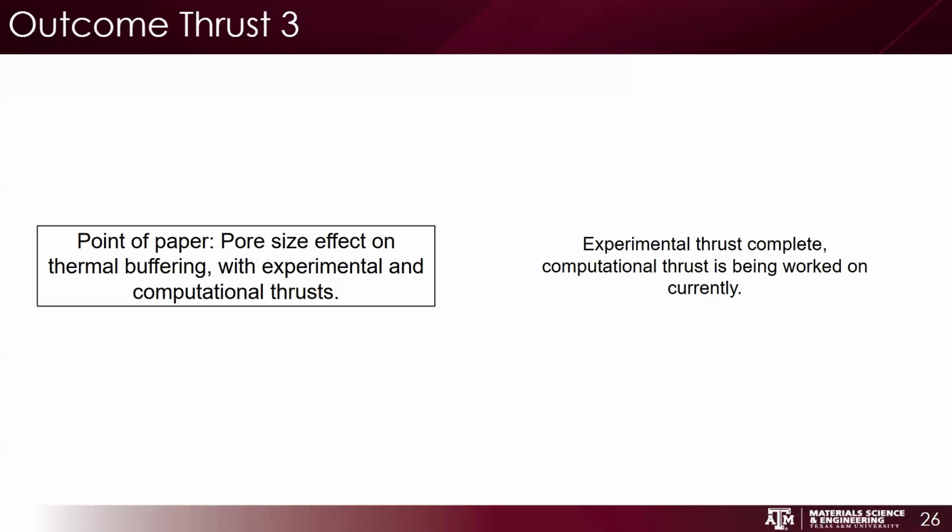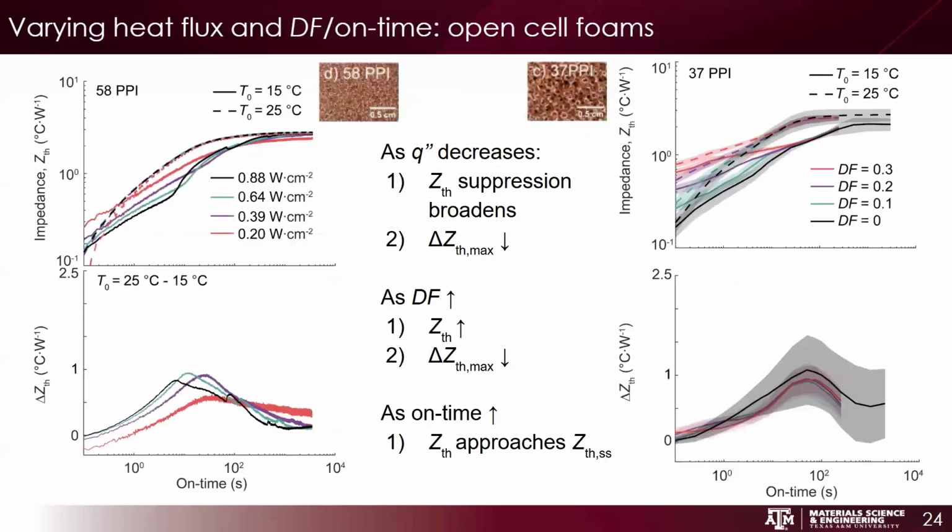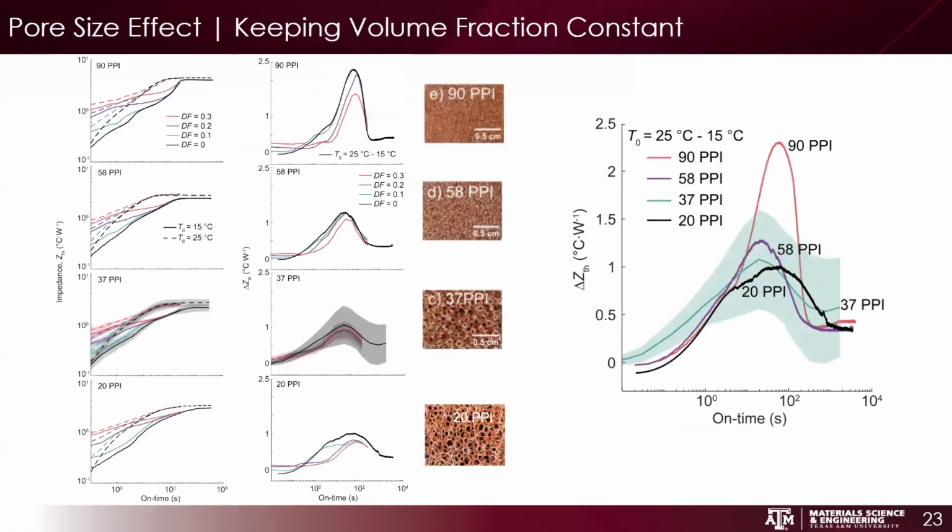So what are the computations? What are you trying to answer with that? What are the melting dynamics of the system? Is this 1D heat transfer, 2D heat transfer? Are we within length scales of a regime where it's 1D to 2D heat transfer, or are these pores large enough that maybe there is convection within the system and now we're not in a regime where that convection is suppressed?